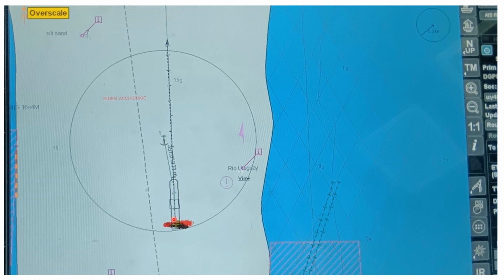A slight dragging, just a few meters that your anchor is dragging. Let's say you drag by 10 meters or 15 meters, then it will already alarm. It will produce alarm because you are already outside the swinging circle. That is if you don't put any allowance.